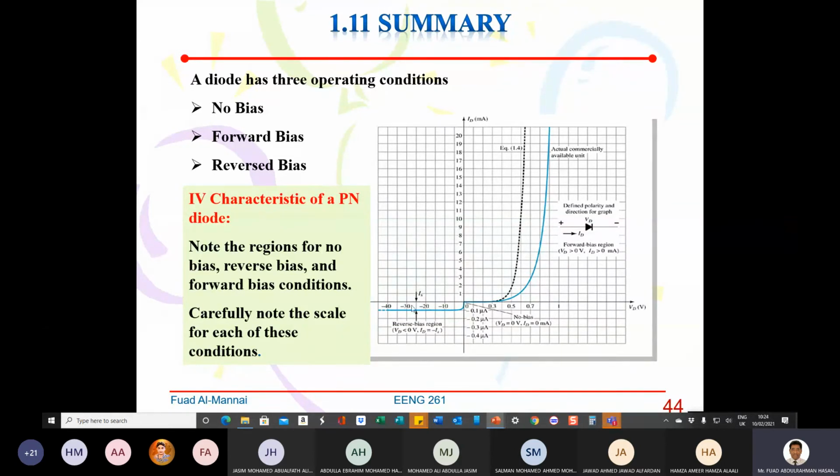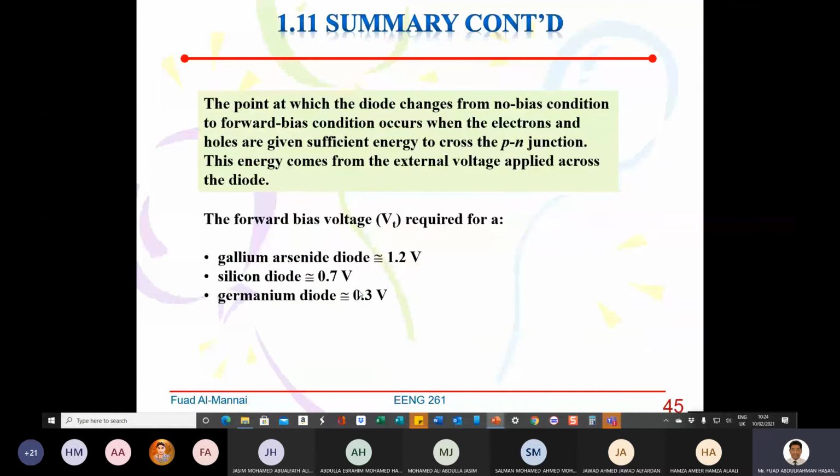Over here to the left is when the diode is reverse bias. That means it's almost open circuit. And there's a small current here, called IS, and it is around 0.1 microamp, very small, or we can call it 100 nanoamp. So we usually ignore that. Guys, any questions?